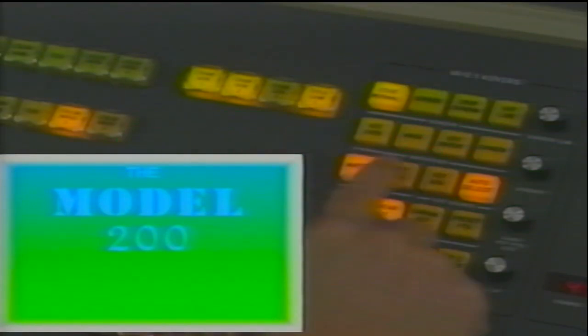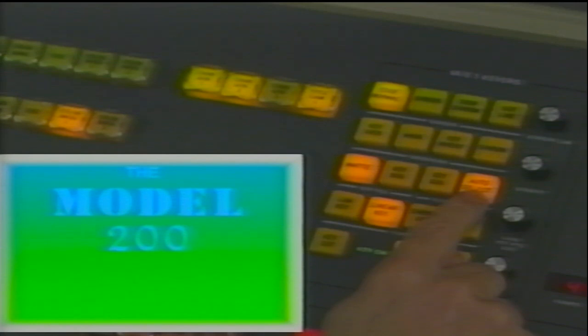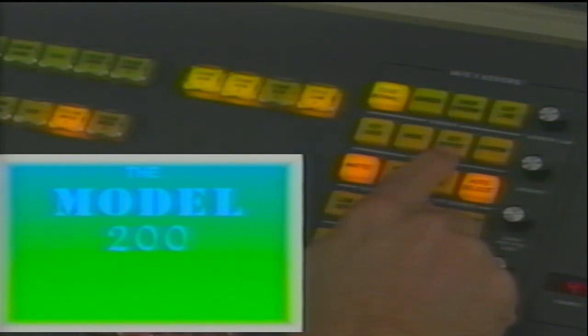Personality programming allows each of the primary and external key fills to call on one of the 6 external key sources to generate the key. These external keys can have multiple assignments. When a fill source does not have an associated external key source, self key can be assigned. In Auto Select, the Model 200 system automatically selects the assigned key signal when the key fill selection is made, freeing the operator from any additional action.